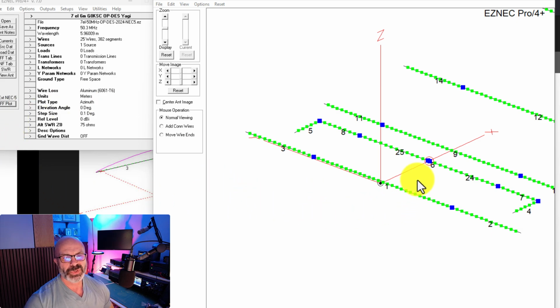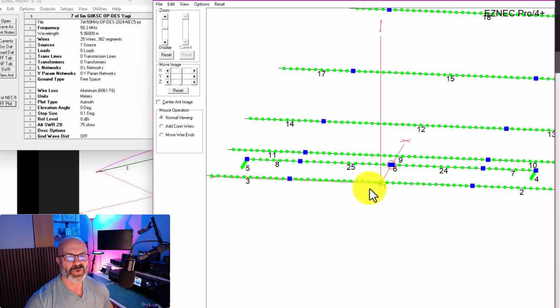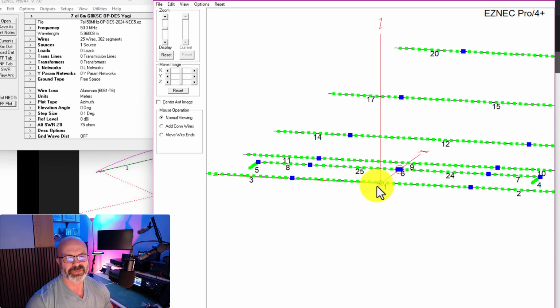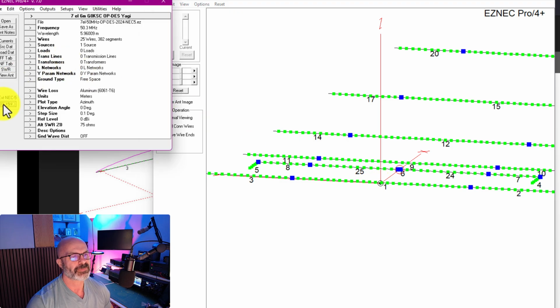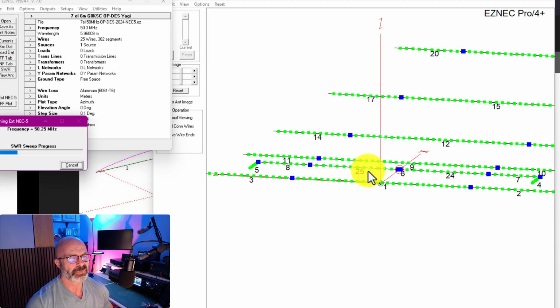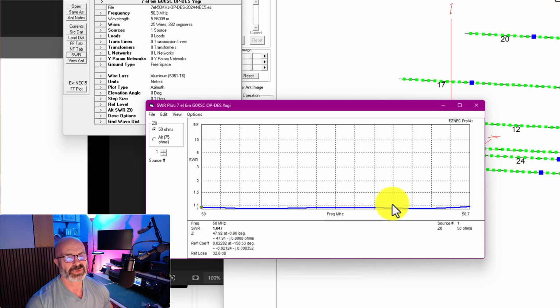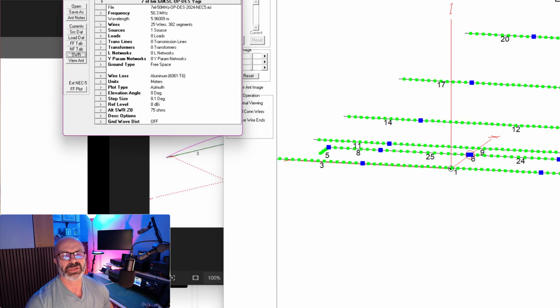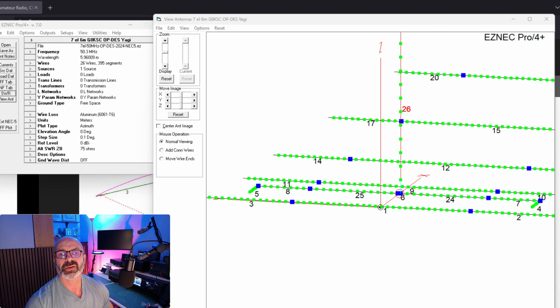So this is just the pure clean fed dipole that would be theoretically fine with a balanced feed point. So we've got 12.19 dBi, a nice clean pattern, and SWR is all hunky-dory and nice and clean. We've got that nice wide flat dip that we saw a few weeks ago. So let me go and return this piece of coax back on again. I'm going to need to get it down to a point where, that's it. I think that's where we are.